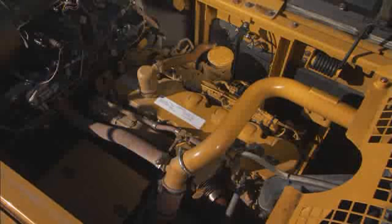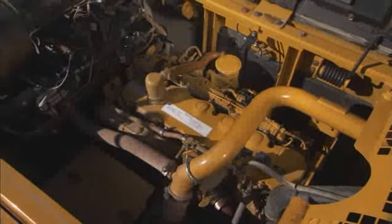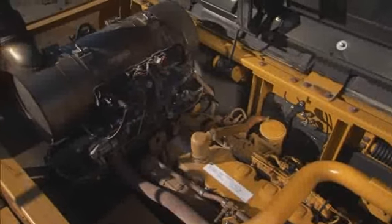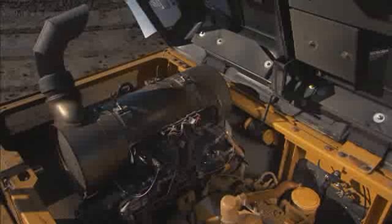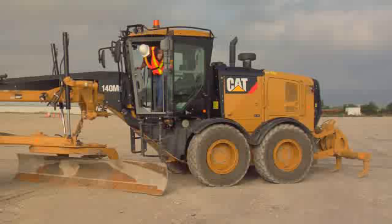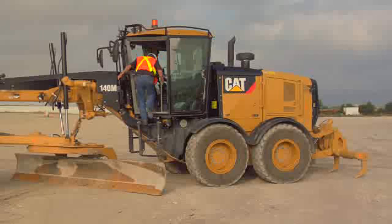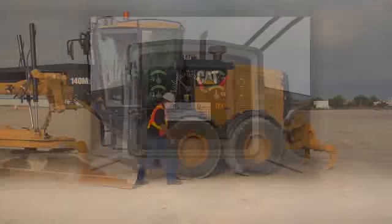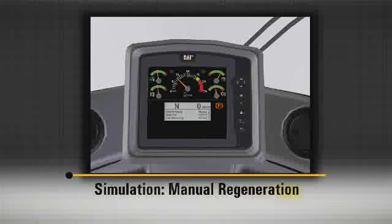If you break for lunch and the ECM initiates regeneration, be careful when you return to work and do your walk-around inspection. When checking fluid levels, there are components in the engine compartment that may still be hot. Also, when regenerating while on break, someone must always stay within 25 feet of a running machine to meet U.S. OSHA worksite regulations. This simulation demonstrates how manual regeneration occurs.